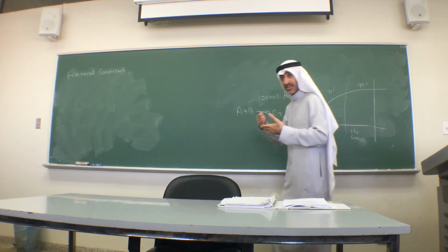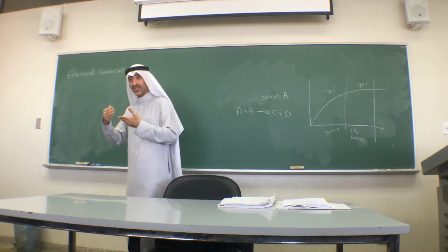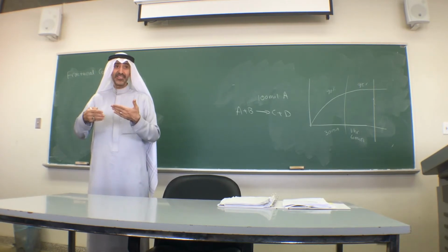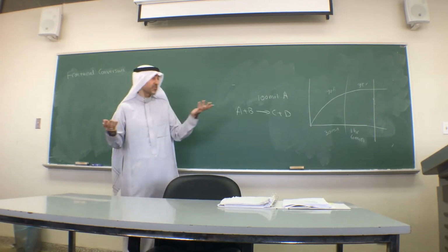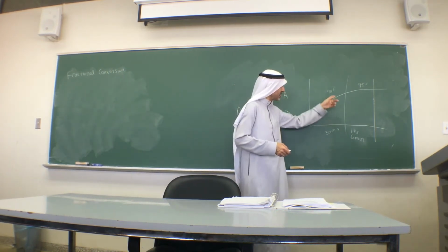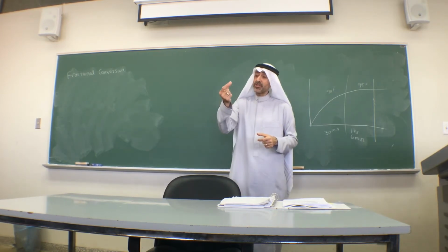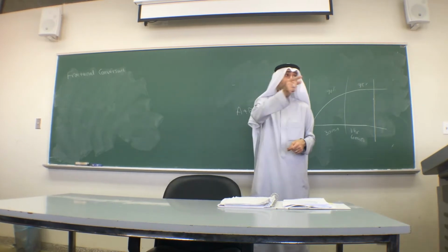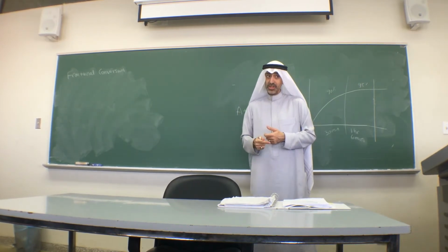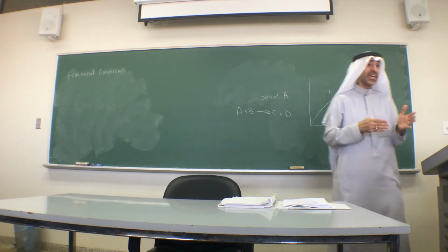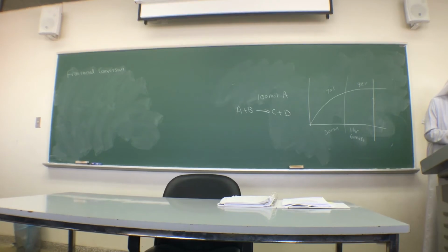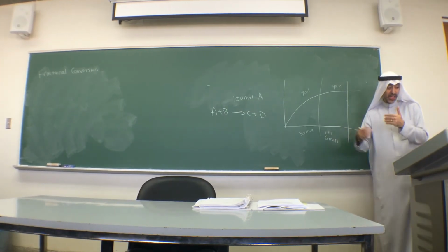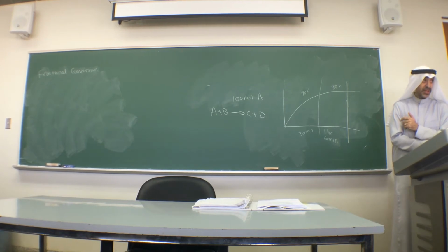Of course, time is energy, right? Because you are running the reactor, so you need to put in money. Is it worth it or not? Sometimes you look and say no. After 30 minutes, you have 90%. The 10% that did not react, take it and recycle. So no need to wait. That's why usually when they design the reactor, they don't design it for 100% conversion, because it will take a long time. Clear, guys? Accordingly, an amount of the reactant will be left in the reactor with the reaction product.